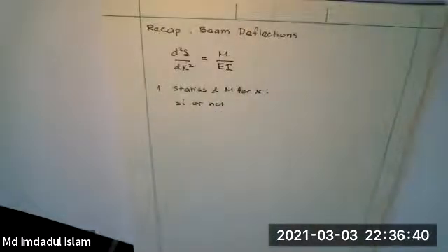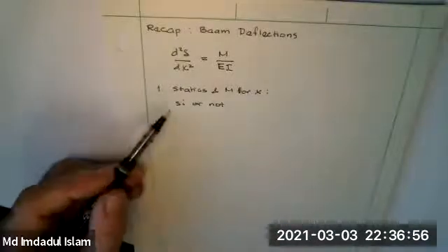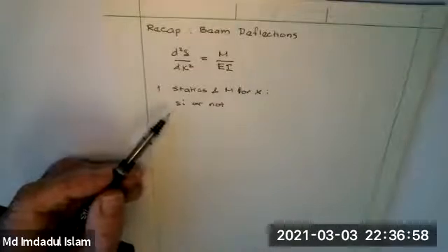Most of this analysis is 2D. There are 3 equations of statics in 2D. Sum of the forces in the x direction or horizontal direction, sum of the forces in the vertical direction, and a moment. Okay? You can exchange these for 2 moments and 1 force, but in terms of making this decision, you want to think of 2 forces and a moment. That's all. Okay.